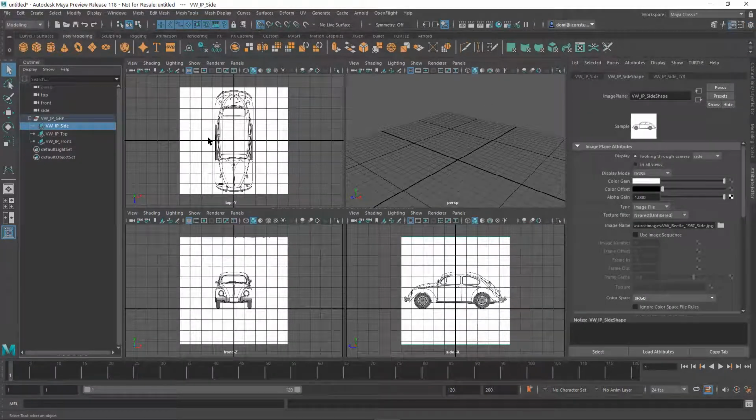And sometimes you may not want these on full power, okay? So that's kind of like your transparency. So we've controlled what cameras it's looking through, but now we want to change its transparency, which is down here in alpha gain. So you can mess around with the slider. I mean, if you want to just look, so then you can visually see what's going on in the view, right? So I'm gonna pick 0.5 just for now, okay?